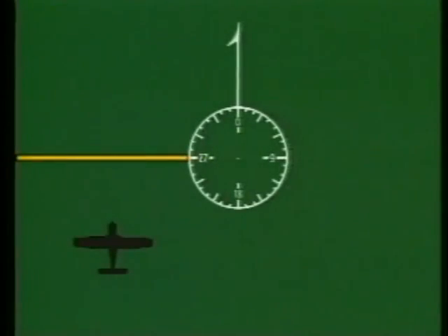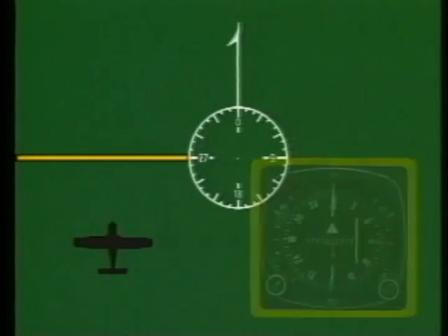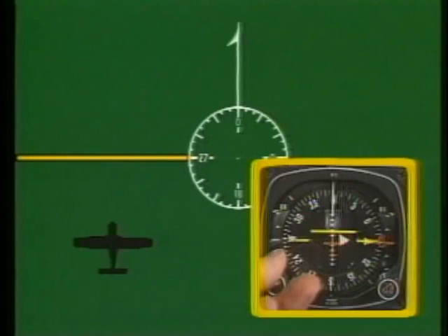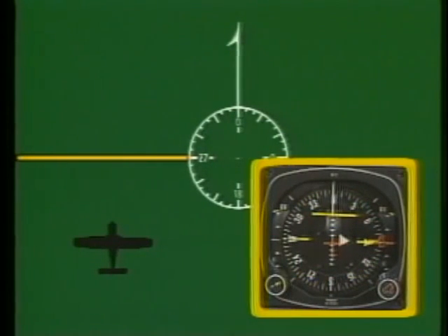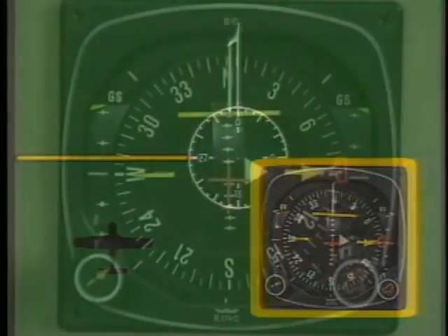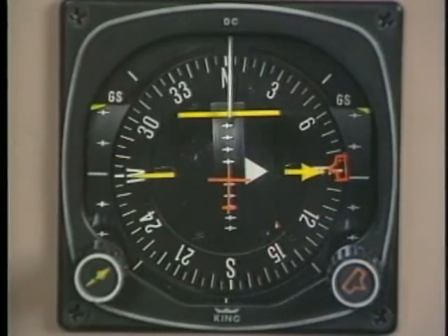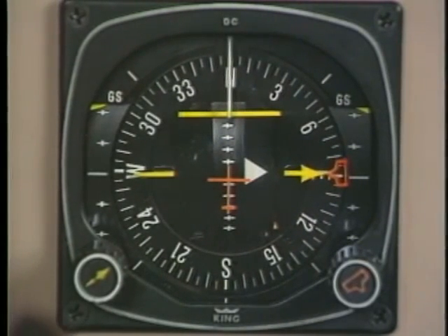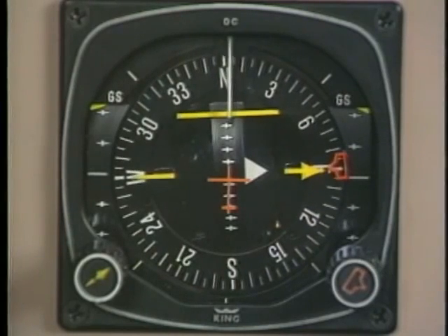To see how easy the HSI is to interpret, assume you are southwest of a VOR on a heading of 360 and want to intercept the 270-degree radial and fly inbound to the station. The first thing you do after tuning and identifying the station is to set the inbound course of 090 degrees. Notice the ambiguity needle shows that this course is to the VOR. With an HSI, it is easy to visualize your position. The relationship between the miniature airplane and your intended radial is shown by the lateral deviation needle.